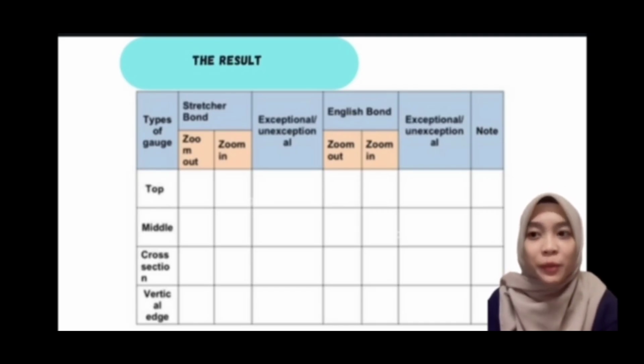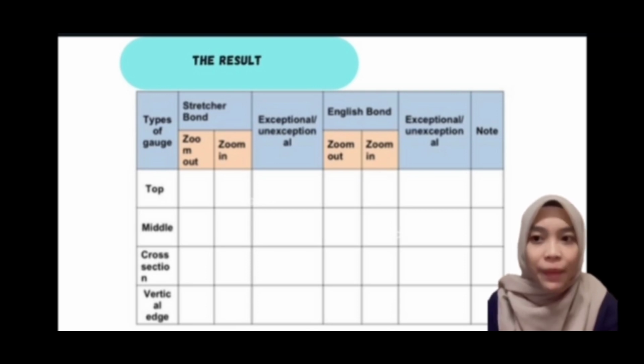Stretcher bond, the most commonly used bond in the UK. A pattern is made only using stretchers, with the joints on each course centered above and below by half a brick. This type of bonding is not particularly strong. A variation is the racking stretcher bond. The overlap between bricks is usually a third or a quarter of a brick instead of half a brick.